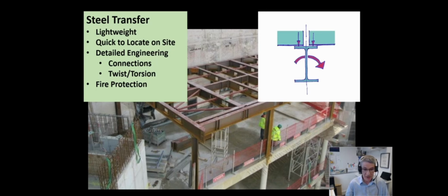In terms of design or detailing, the deflections need to be carefully considered. The loads may not be centered on beams, so the beam outstands may need to be stiffened. There may be unbalanced loadings on both sides of a given beam, either during the placing or in the final configuration. The addition of fire protection to the steel structure is another operation, and the underside of the lowest level of modules are more exposed than with a concrete transfer slab.